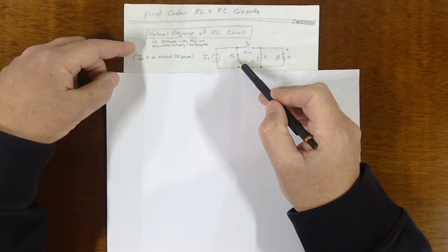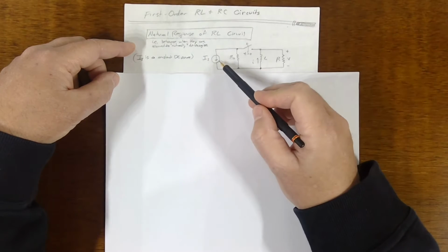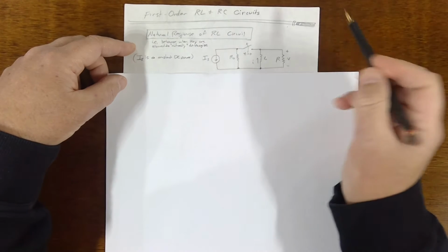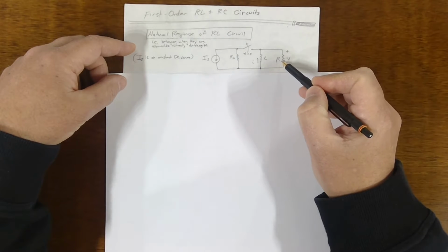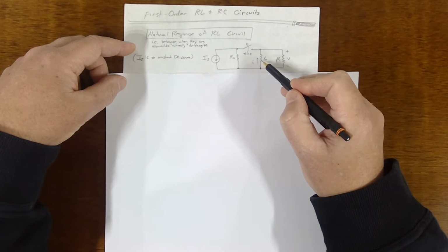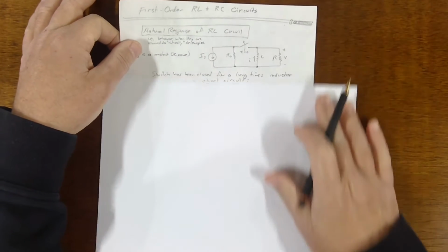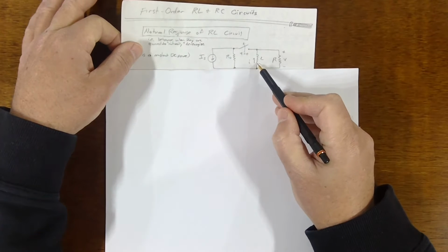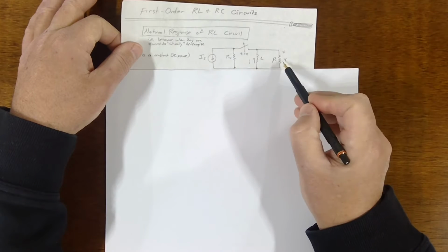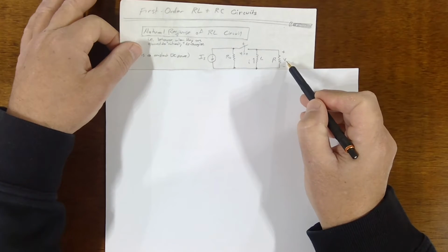And there's this R0 resistor in here, which you may or may not need. Generally speaking, it depends on the nature of this power supply, if it's a battery or could be other things. So you might not need this R0. And then this RL is the load resistor, the element that's going to take the energy that's stored up in the inductor and use it up, turn it into heat. So there'll be a current I, little I, through L, and then there'll be a voltage across this resistor with this polarity, the voltage V.